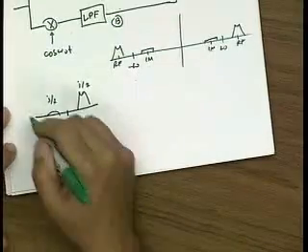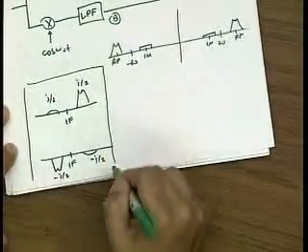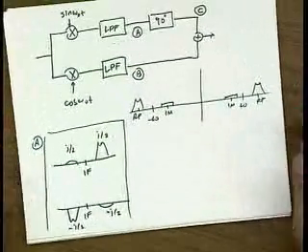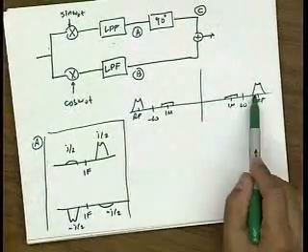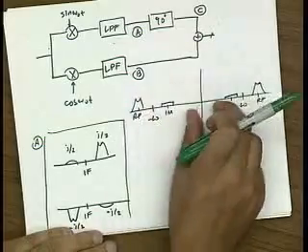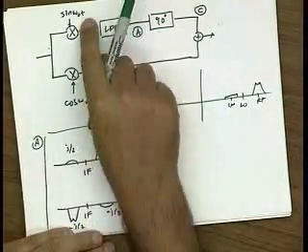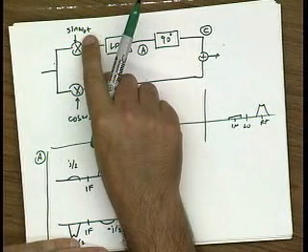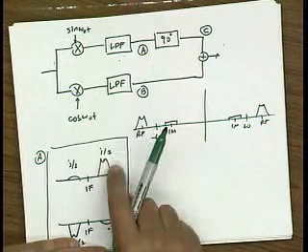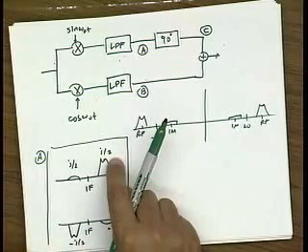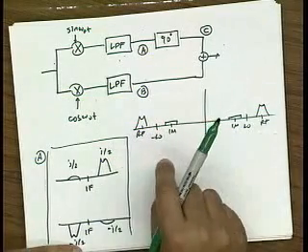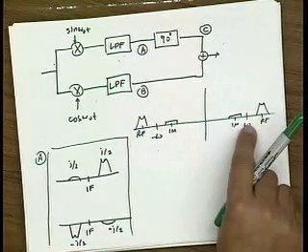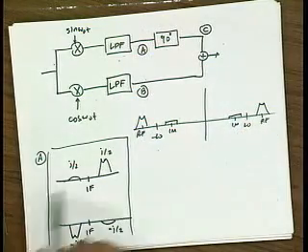These are the waveforms which are summed together, and I'm keeping them separate at point A. The first term corresponds to just shifting this down to IF when I multiply by e to the plus j omega naught t, and there's an extra factor of over 2j. The second term corresponds to this being multiplied by e to the minus j omega naught t.